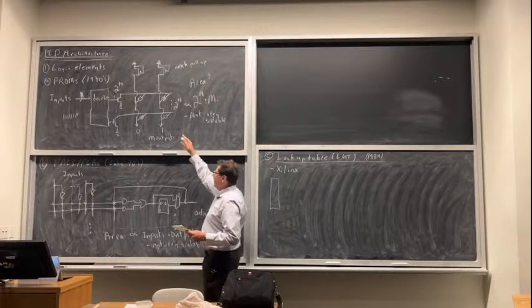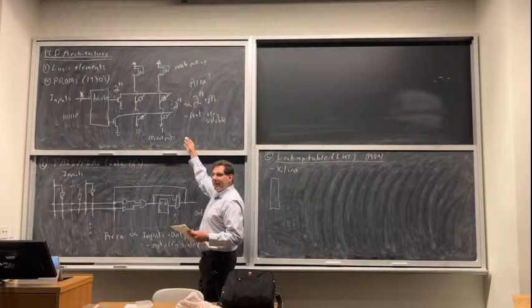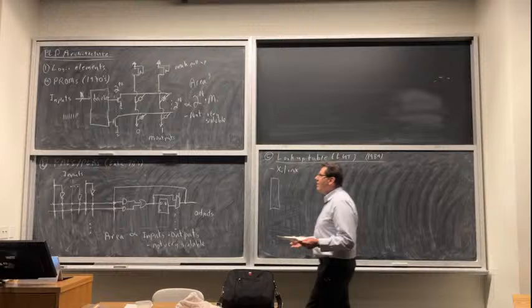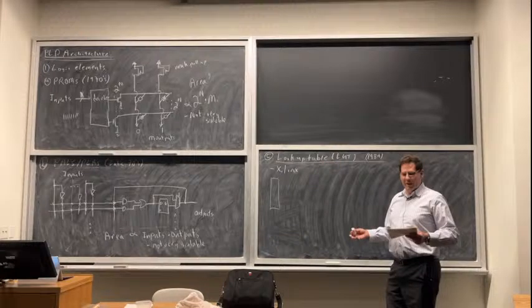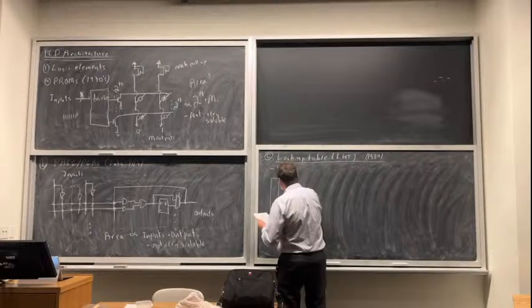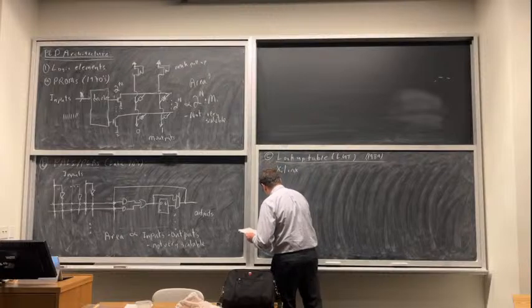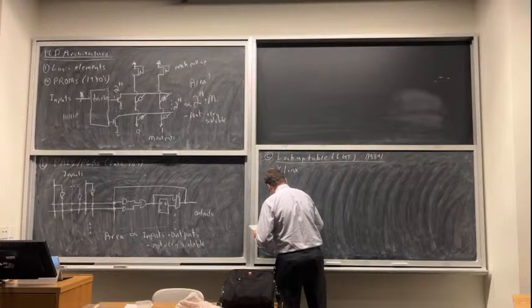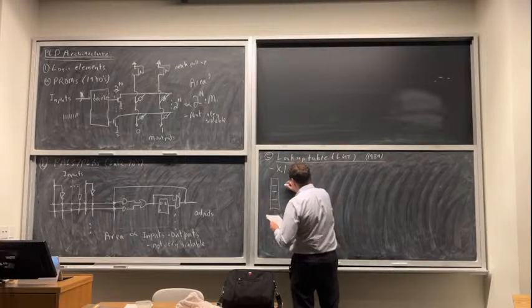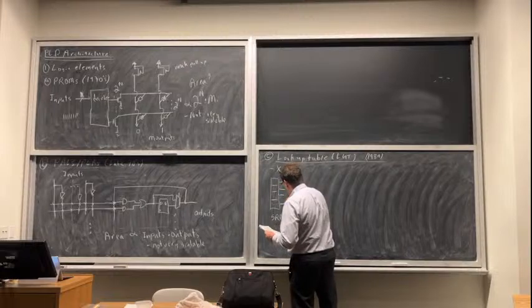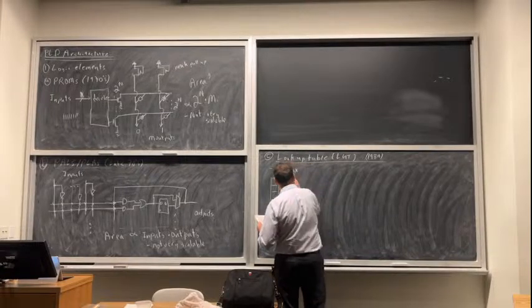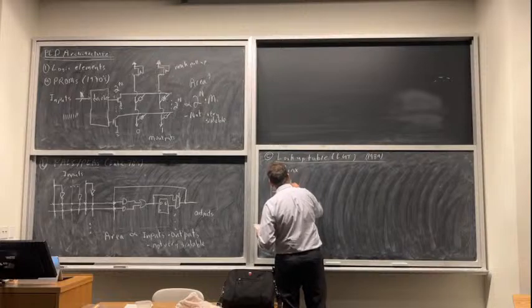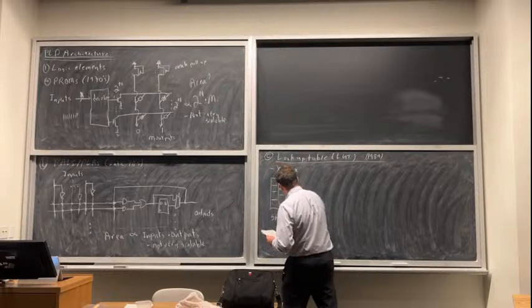So it's kind of building on this idea. It is a form of read-only memory, so it is related to that. And we already talked about this. So it's basically an SRAM, and you follow the SRAM with a multiplexer. Okay, so this might be the 0,0 data item. This might be the 1,1 data item.